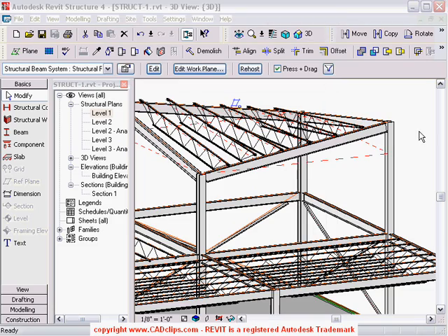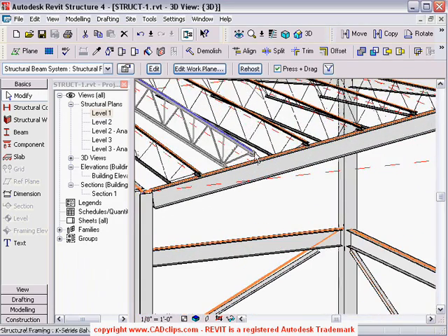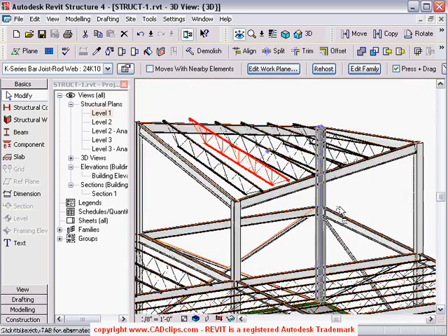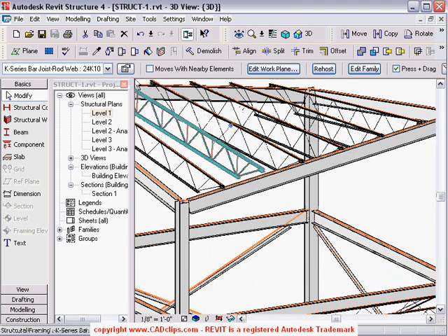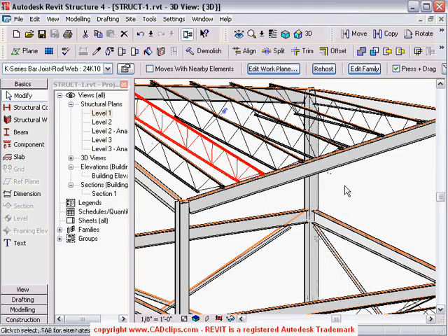And then it'll turn those into joists, which is quite nice, and I can see there's a problem with this guy inside of here. I need to fix the offset of that guy. I'm going to go back into here and say, oh, I don't know why that one, I've been playing a little bit, should be only a 4-inch offset, so I can fix that one up there.